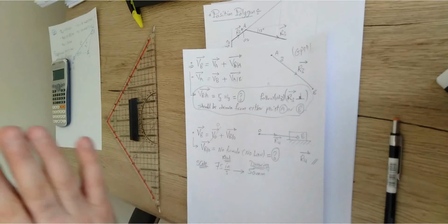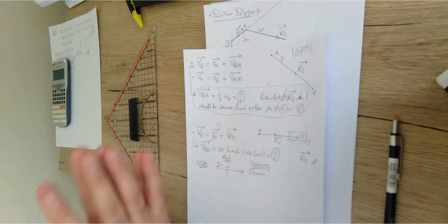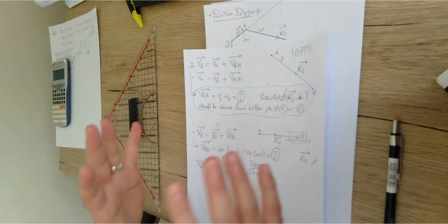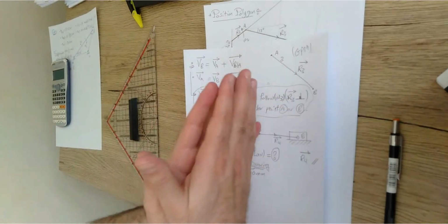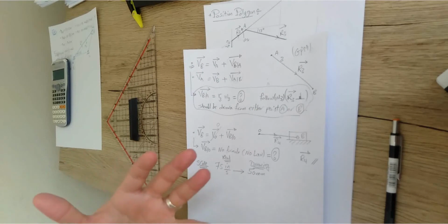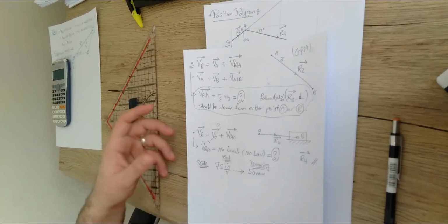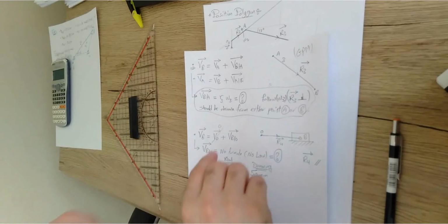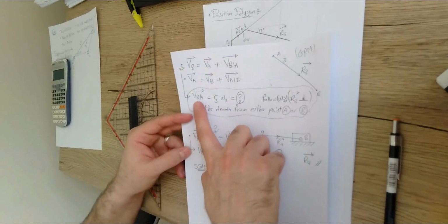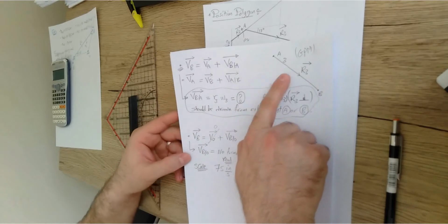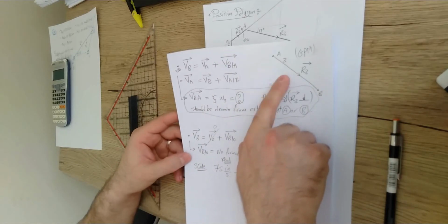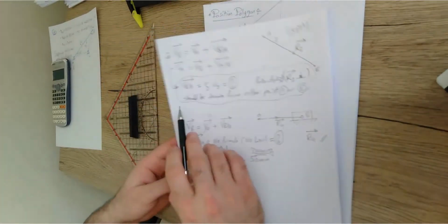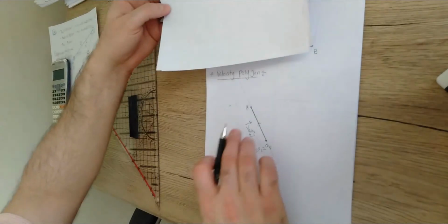This line should be a locus for the other point. So in case you have a velocity vector with unknown magnitude and direction, in many cases, especially if this is a link that rotates, you can only draw one thing, which is a line. This line, in case this velocity vector belongs to a link that rotates, whether general motion or fixed point, should be perpendicular to the R of this link, right? And it should be represented from either A or B. We already have point A. So what does it mean?